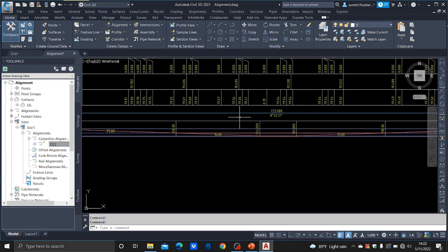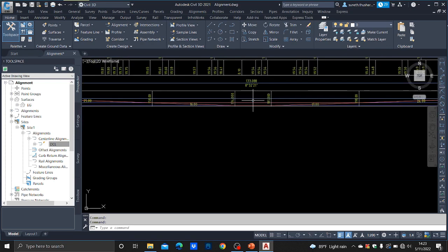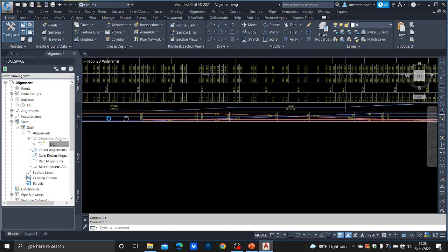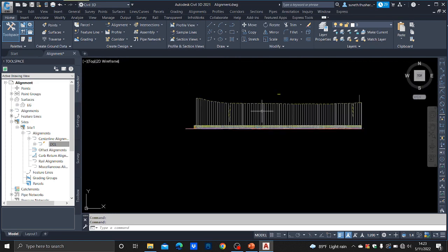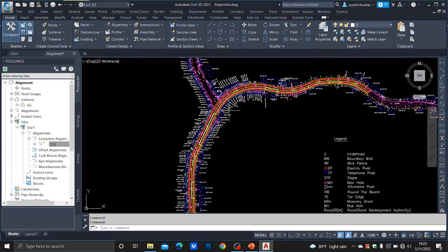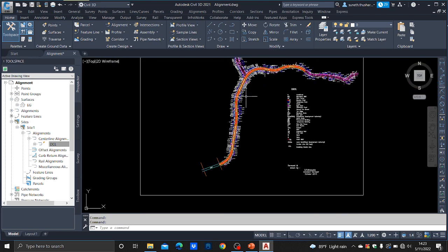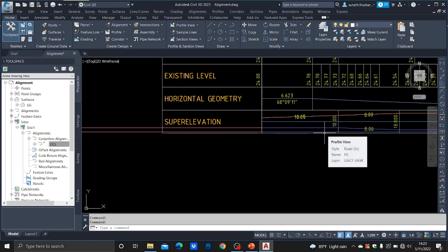superelevation, right? Can you see that this is a mess? Okay, this is almost a mess here, because you see so many superelevation values here. The reason is that they do not consider the compound curves or reverse curves. They consider each curve as an isolated curve. So this is a problem. So we'll remove this here.